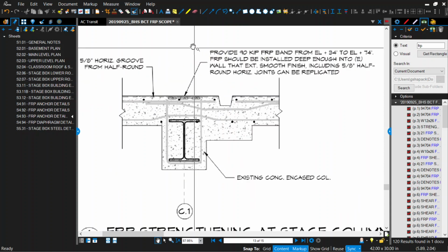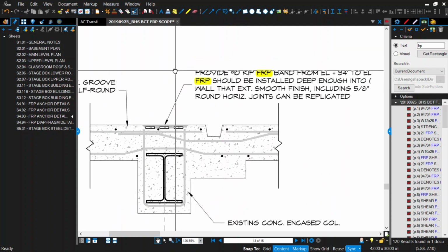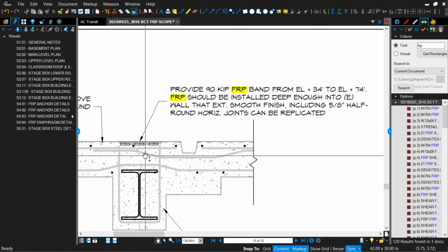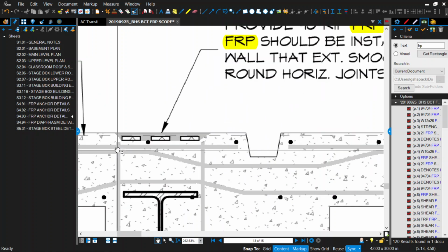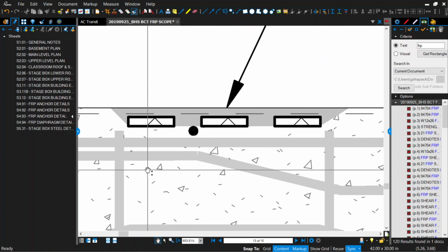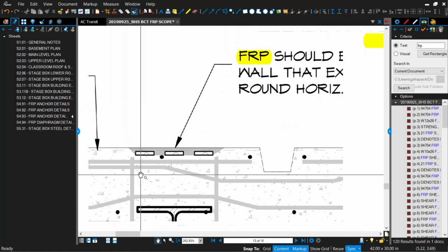What is this? They showed FRP recessed here. Or depressed. So they want to chip out the concrete, it looks like. They want it lower in. Install FRP fabric, or then laminate? Is that fabric? That's the way they showed fabric on plans, so I assume it's just fabric.